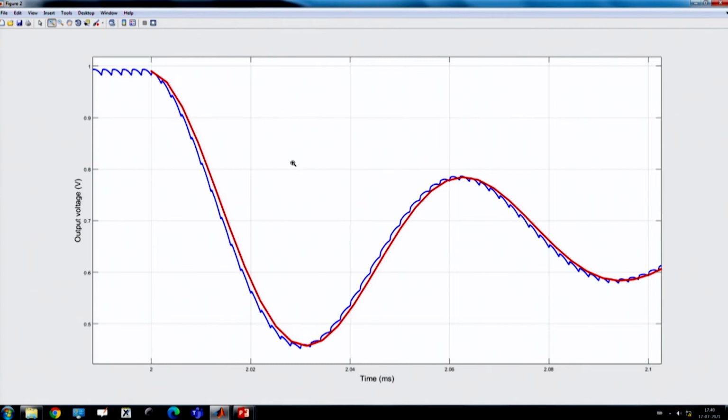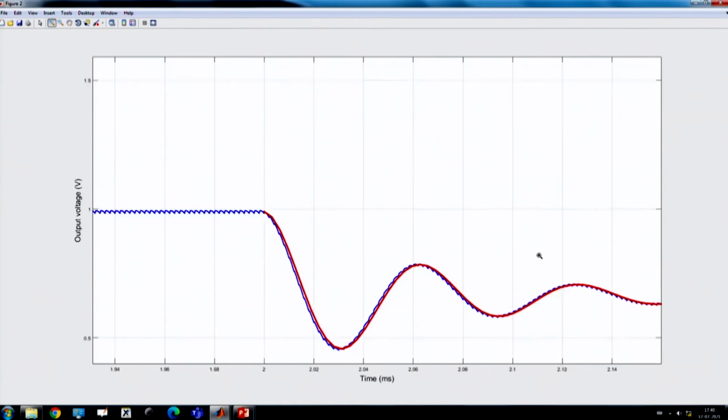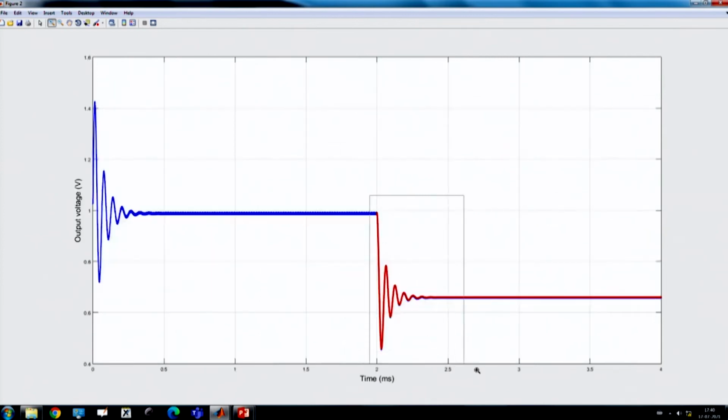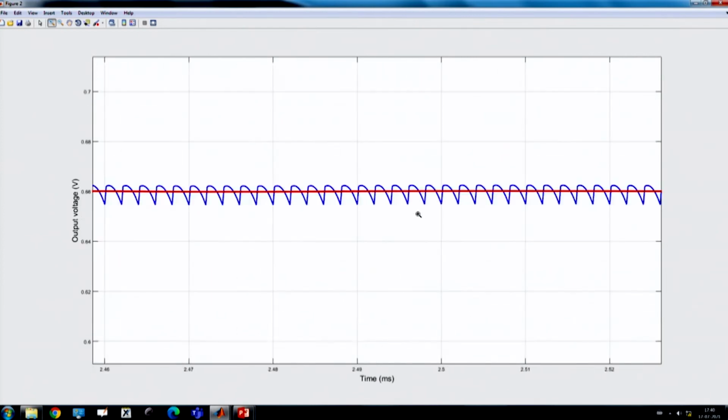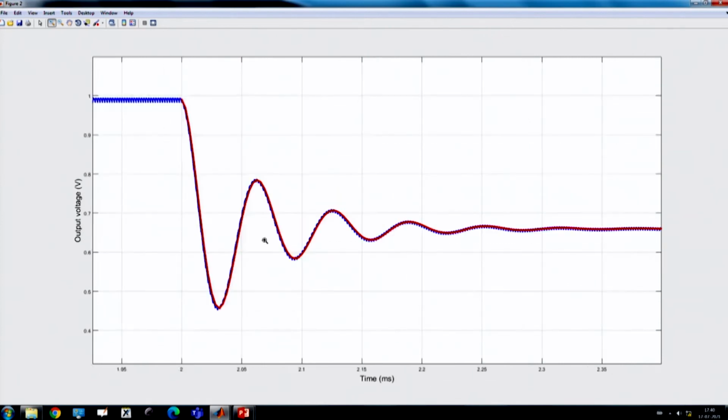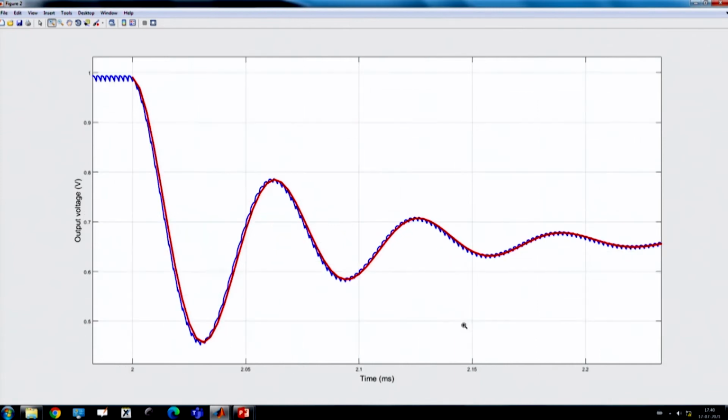Almost nearly they are matching quite nicely. So, we can assume that this model works fine. There is a small deviation, because in the audio susceptibility expression there is a duty ratio D. So, we have to update the duty ratio in order to match this. That is why a slight shift is happening.